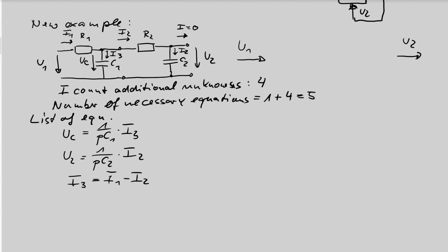We have a network with elements C's and R's. So we of course then can write down the mesh rules or the loop rules of Kirchhoff's law. So the voltage in a loop, the sum of the voltages must be 0. This expressed in the first loop is U1 is this voltage plus this voltage.